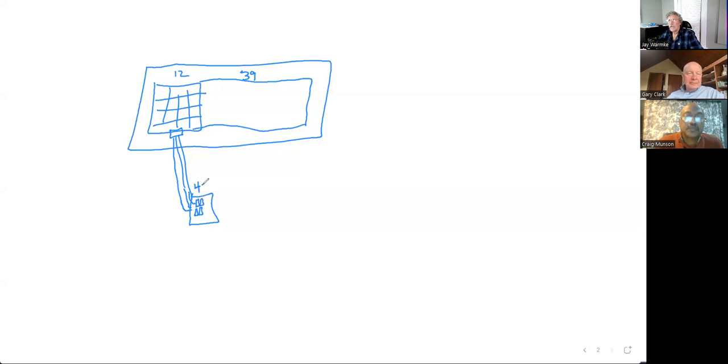So 4 times 20 amps, at that point the output of this box could be 80 amps. So why not put in wire already big enough to handle 80 amps? Absolutely, where you'd maximize that. And then when you come to this AC disconnect, normally those come in 30, 60, or 100 amp flavors for the AC disconnect.